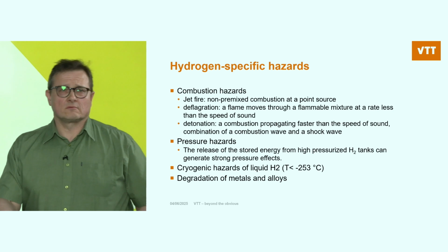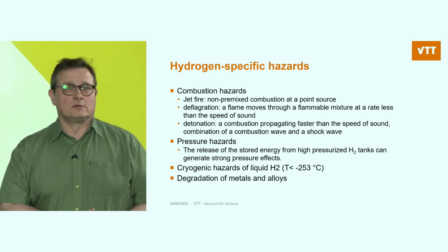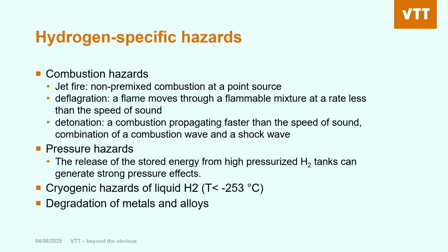First, I'm not going to talk a lot about general hydrogen hazards, but just to remind you that we are dealing with a quite interesting substance here. Combustion hazards are of course the main part. Jet fires and different kinds of explosions like deflagration and detonation, which is the most severe if detonation occurs.